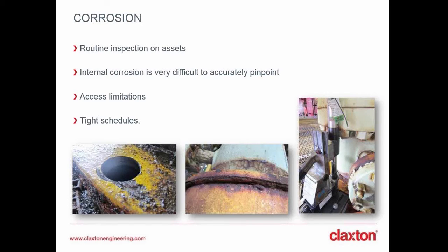There are two approaches to addressing this type of problem: the inside out and the outside in approach. The inside out approach is a lot more difficult as you don't really have visibility of the operation. Apart from this challenge, if you're trying to remove damaged casing or conductor, if the internal casings are cemented, then you won't be able to cut and retrieve the internal string, nor confirm if the condition of the pipe left after the cut to run over overshot is good enough for the expected life of the structure of the asset.